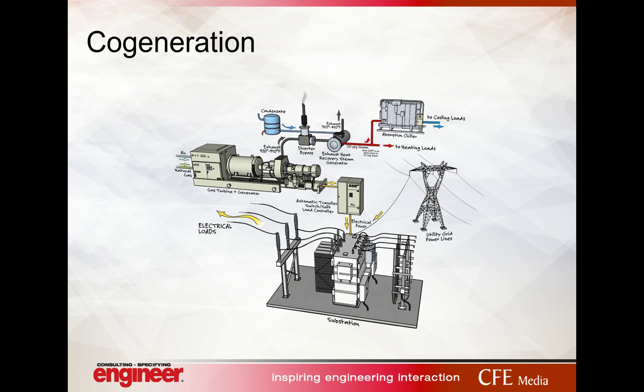Cogeneration, similar idea to what Jeremy was talking about with heat recovery chillers, except now we're using a generator to generate electricity, and then we're capturing the waste heat off of that to reduce all of those reheat loads from our potential VAV or even constant volume systems.